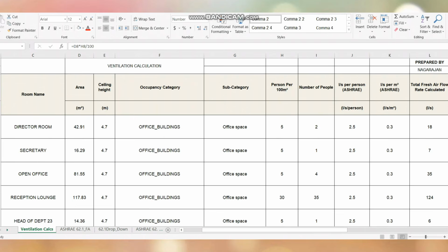So as I told, you can follow the ASHRAE 62.1 for the number of people counting. Otherwise, you can follow the architectural seating method to find out the number of seats and number of people. So in this video, I'm going to follow the number of people based on the ASHRAE 62.1. And after that, the number of people, I have the formula here, because here the concept is for the 100 meter square, it is 5 people.